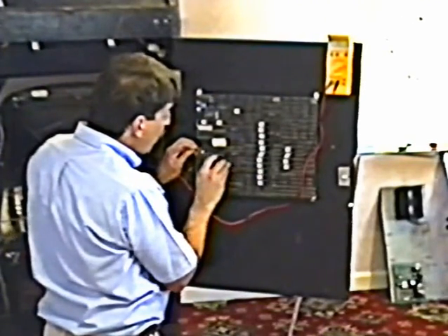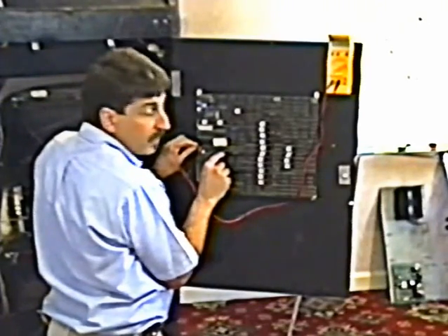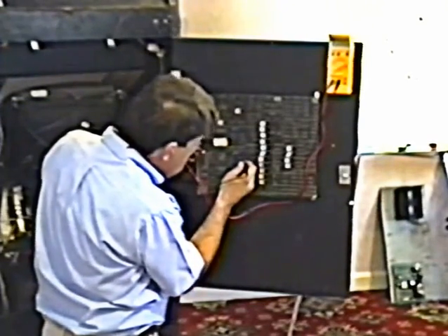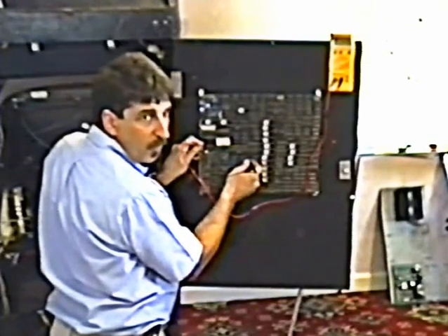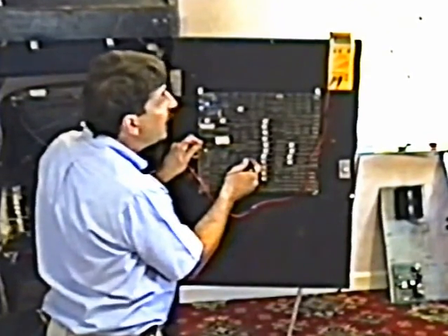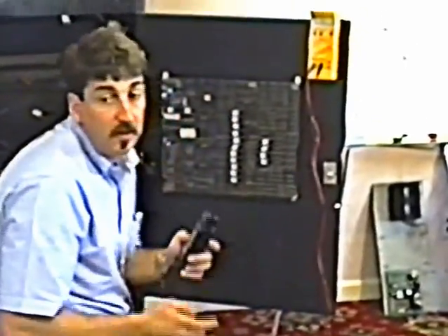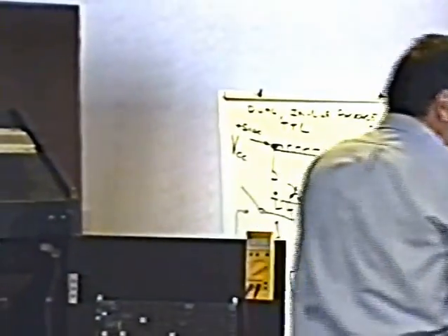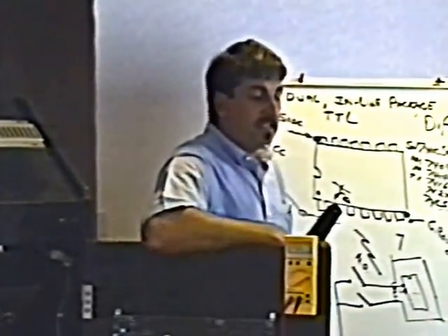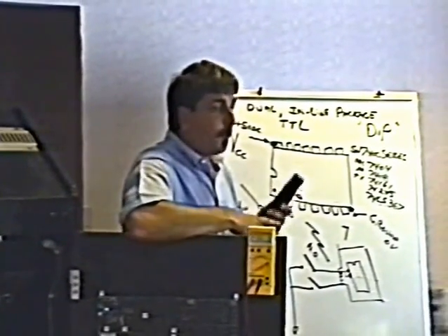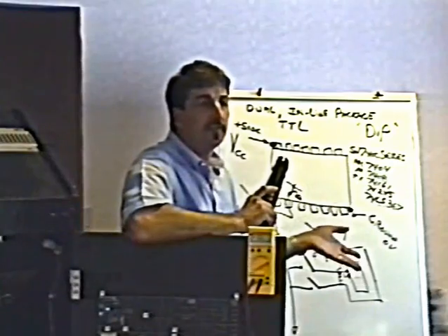Now, naturally, the ground pin will show you 0, because you're on ground on the other side. The power pin, the plus 5 volt pin, will also show you something very low. That's not what we're talking about. We're talking about all the other pins, the ones you check. And I can almost guarantee you that you will find the bad IC this way. It works really well. This particular method of finding bad ICs works so well that I have virtually abandoned my conventional troubleshooting techniques.